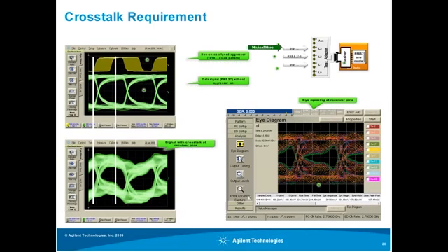On this slide, I have a little example for crosstalk, which is actually from a real device. So I'm sending a PRBS 7 pattern to one lane and a high-frequency clock pattern, so that's not the compliance test clock pattern, to the adjacent lanes. And you see the clean PRBS here and the high-frequency clock pattern. And I may have forgotten to mention that on a previous slide. One requirement is that that clock pattern is not phase-aligned. So you see the clock pattern moving over half of the UI of the PRBS 7 pattern.